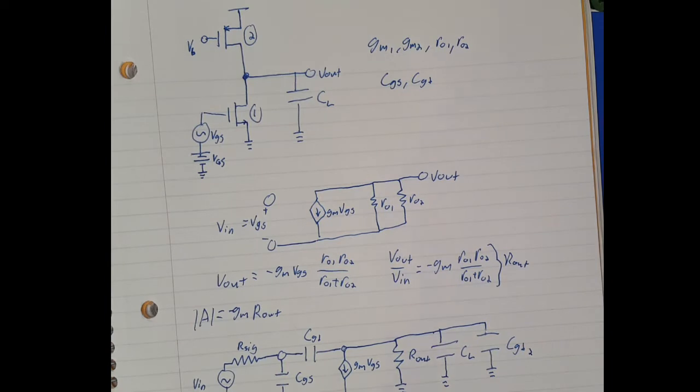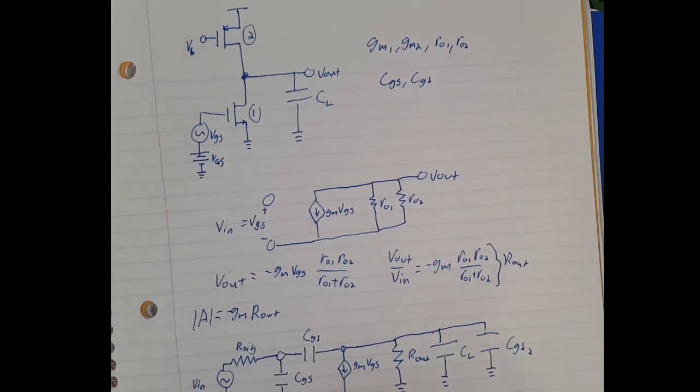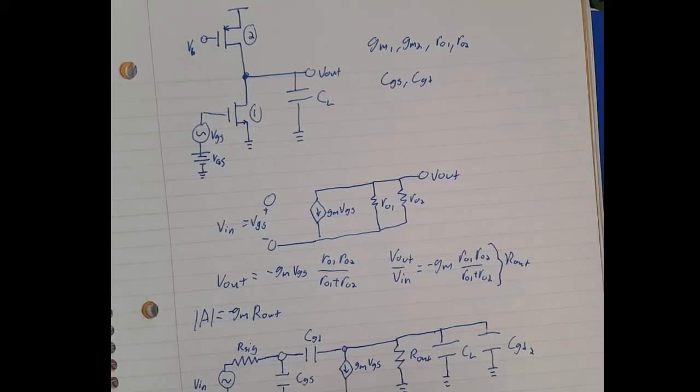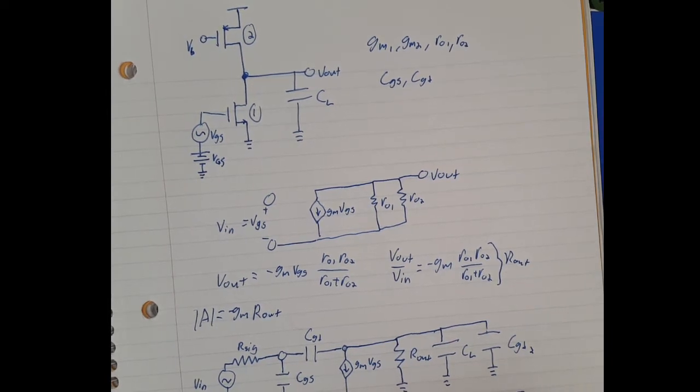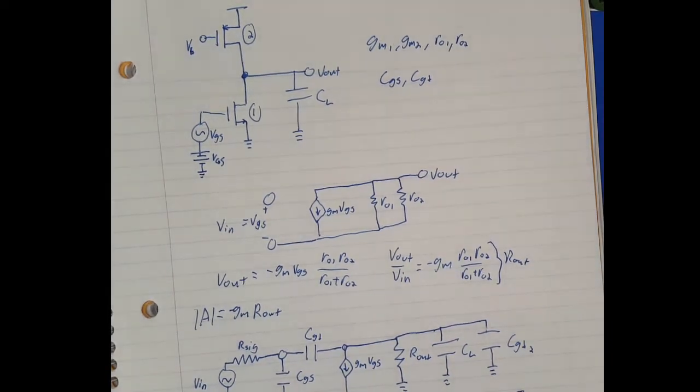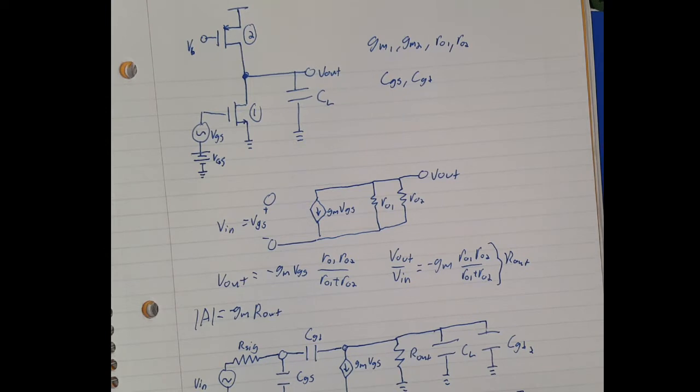So how do you do this? Well, first of all, you get Z1 equals Z over 1 minus K, and you get Z2 equals Z over 1 minus 1 over K. And that's just doing this, keeping current equal to this, and calculating it out.